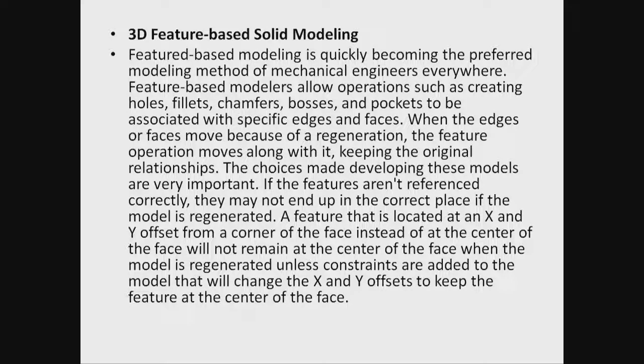3D feature based solid modeling is becoming the preferred modeling of mechanical engineers everywhere, especially for things which involve fabrication using conventional fabrication processes. Feature based models allow operations such as creating holes, fillets, chamfers, bosses, pockets to be associated with specific edges and faces.